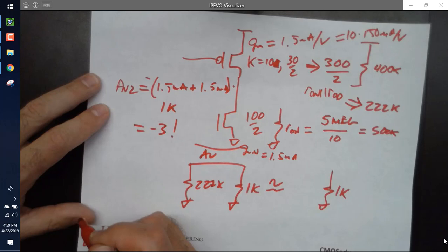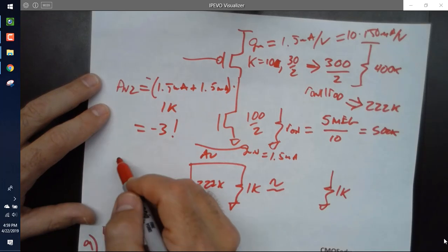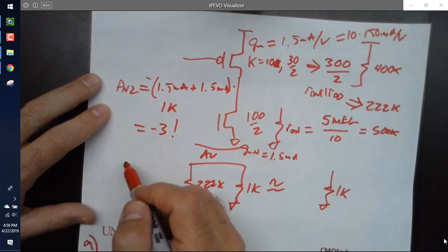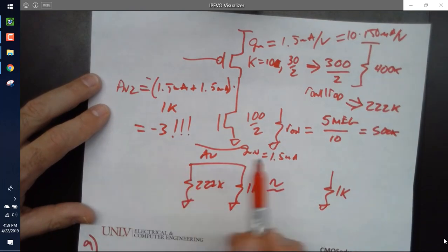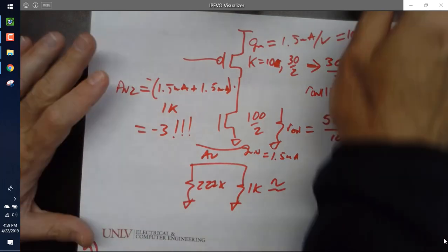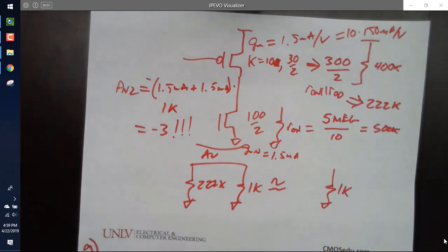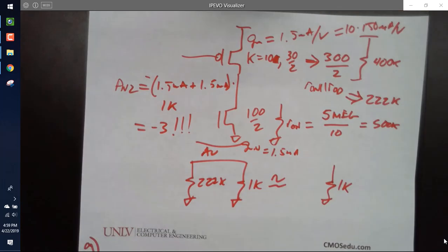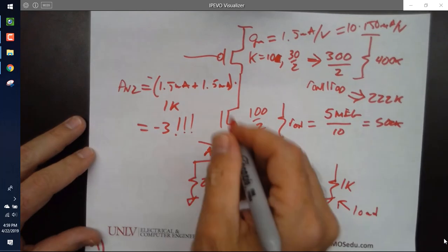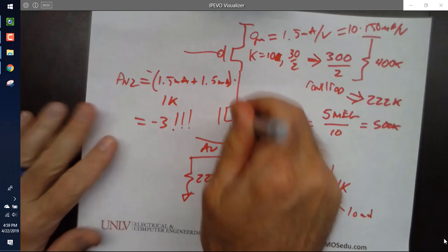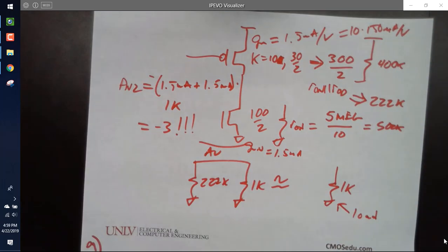So now my first stage gain was... How about this? All right, if my first stage gain was 200, now my gain's gone down to 600. That's our load. Isn't your spec in your projects to drive 1K? Okay, but we're going to talk about that a little bit more. Does everybody see? So you might decide I need to beef up the output stage a little more.